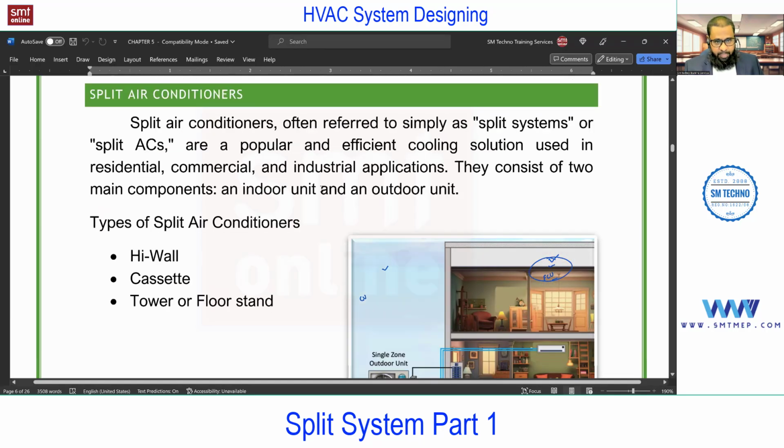So here you see split AC, also known as split system or the split AC in actual practice. And this also comes under unitary system. Window, split, both come under unitary type. Why I'm talking about this unitary? Because you see, if you talk about the ductable package, etc., that comes under central air conditioning system. In that sense, these two units we can consider as unitary. Unitary means unit wise as per the zone requirement. And here I request you to make a note of this point. Please make a note. Zone refers to thermostat.